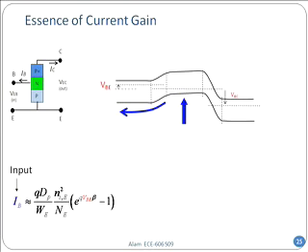So when you push a base current, the transistor must accept that current because you are forcing it to. The only way it can accept the current is by lowering the barrier on the base-emitter side until it has lowered the barrier enough so that the whole current you are putting in through that blue up triangle can flow out to the emitter. So your input is base current, and you are forcing a voltage in response.